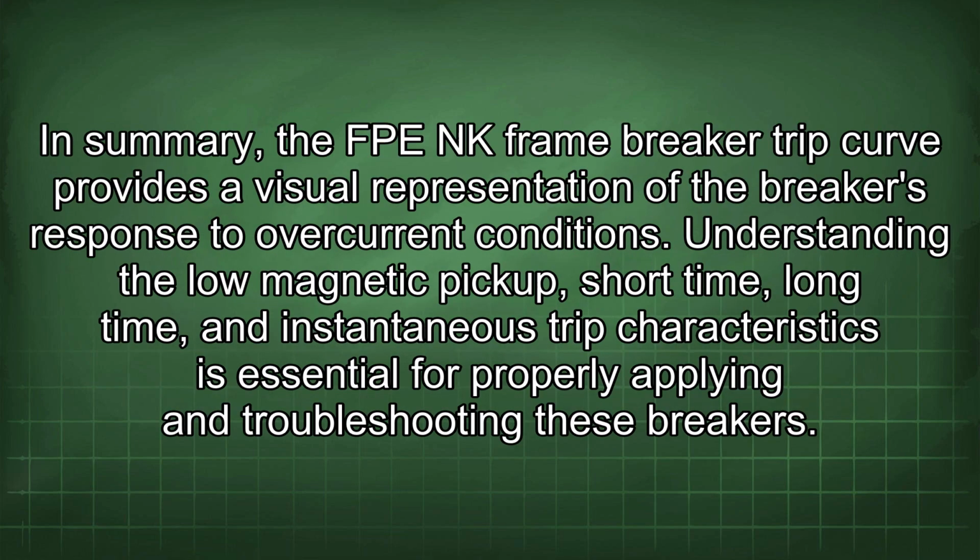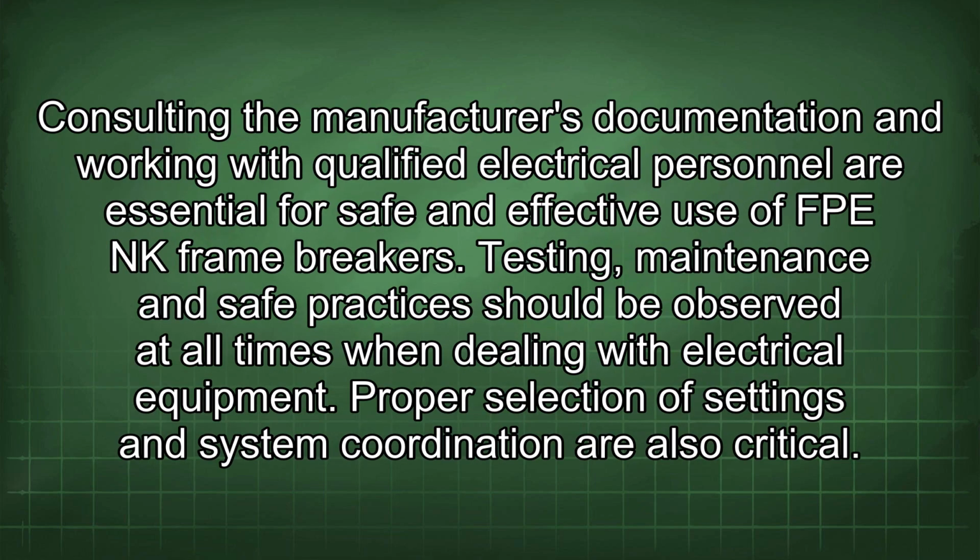In summary, the FPE NK frame breaker trip curve provides a visual representation of the breaker's response to overcurrent conditions. Understanding the low magnetic pickup, short time, long time, and instantaneous trip characteristics is essential for properly applying and troubleshooting these breakers. Consulting the manufacturer's documentation and working with qualified electrical personnel are essential for safe and effective use of FPE NK frame breakers. Testing, maintenance, and safe practices should be observed at all times when dealing with electrical equipment. Proper selection of settings and system coordination are also critical.